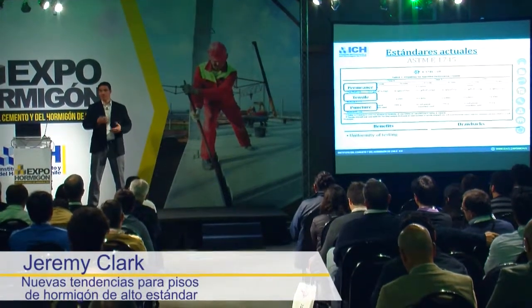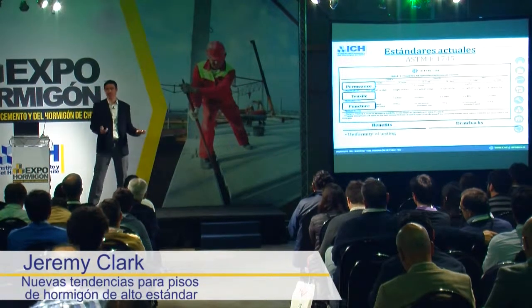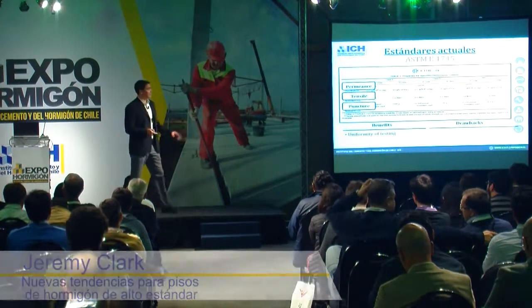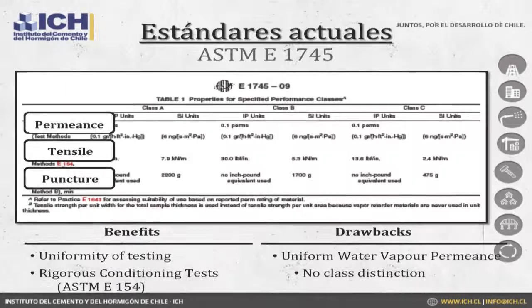Yep, just how much water vapor is moving through the plastic sheet. So the important thing about this standard is that the 6 mil, 10 mil, 20 mil poly that you guys use on the majority of work out there and that we used in the States on the majority of everything that went down probably 10 years ago or so, that product doesn't meet this standard. It lacks the puncture, it lacks the tensile strength, and the permeance is too high. Too much moisture moves through it.